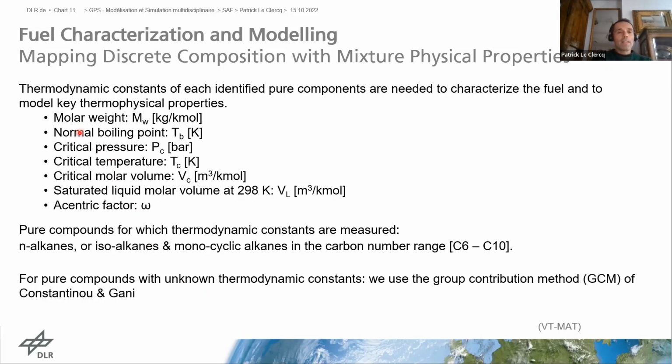Here, a list of these constants that characterize any species, and then often we deal with real fuel. So it's not just one molecule, it's a mix of hundreds of molecules. So you need a mixing rule. So you combine the property of each species with the proper mixing rule, and believe me, it's not just a simple average or weight-based average. It's very nonlinear often if you look at viscosities or surface tensions or others. So this is one aspect.